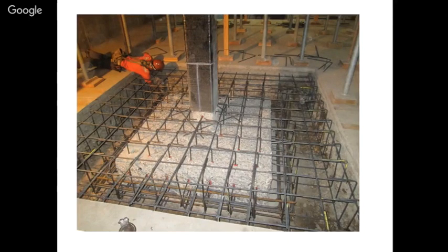And when you do this in an existing structure, we have calculated that the existing structure is not adequate to resist an earthquake. So we are going for earthquake resistant measures using FRP strengthening. Now the question is, when you increase the superstructure capacity but you are not increasing the substructure capacity, then the entire structure will collapse immediately. So when you are increasing the superstructure capacity, simultaneously we have to ensure that the substructure capacity is also increased. Otherwise, there is no use of strengthening the structure.